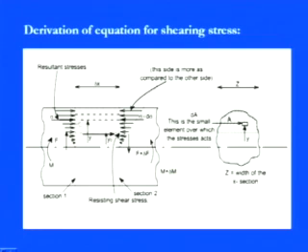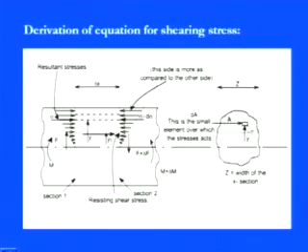So, now if you focus on this element, let us say the y distance is there from this neutral axis, and we have the AB element. Of this fiber, our main focus is that now if you are taking a small element dA, you can see this particular part. So, we have a small element over which the stresses are acting. The description is that it has the area dA, which has a distance y from the neutral axis, and the section modulus is Z for this kind of thing.